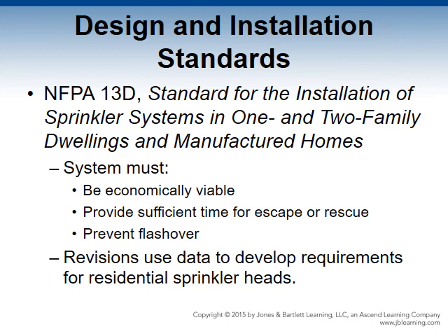Sprinkler head installation was excluded from, of course, small bathrooms, closets, and underneath areas such as attics. The standard established that the system must be economically viable, provide sufficient time for escape or rescue, and prevent flashover. Subsequent revisions of the standard have developed requirements for sprinkler head design, specifically for residential application.